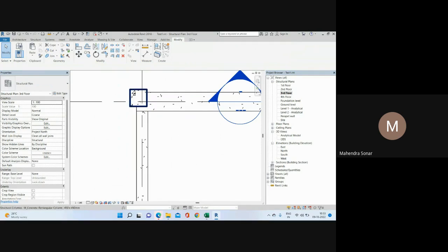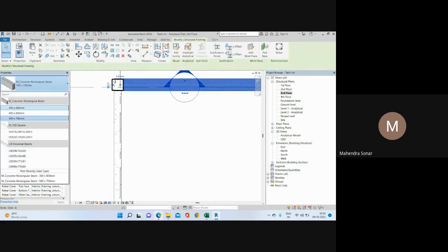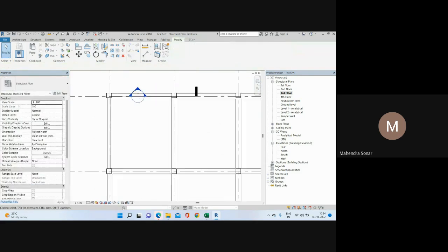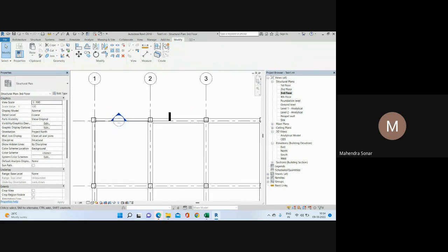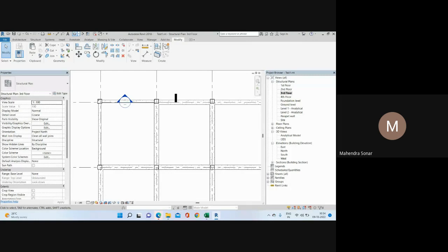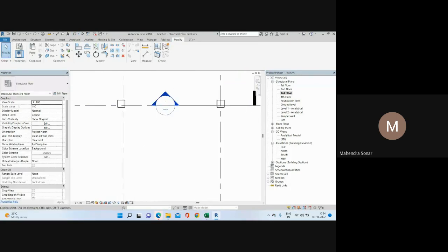Okay, so give the AL command, type AL, and select the center of this column and center of this beam. So you need to align all those beams like that, right? And you need to change the size. Suppose I want to add this, and you need to rearrange all the beams here. Okay, or another, if you change the size, so I will just make undo, right?